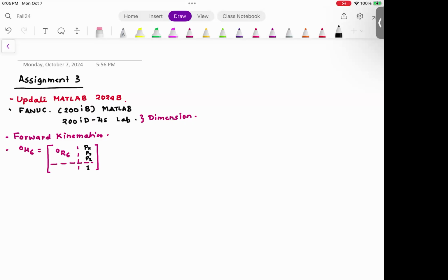For an example, you have this Fanuc robot, and for some weird reason, the coordinate system of this Fanuc robot could be somewhere over here. Okay, that is absolutely possible, because here is what you are doing. You are entering the information in the teach pendant. Teach pendant is giving you the output, and you are trying to compare the output from the actual robot with the mathematical analysis that you have done.